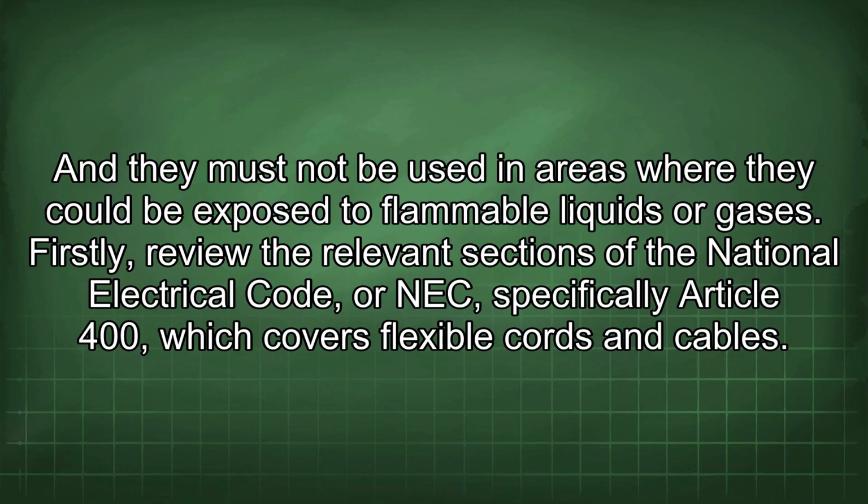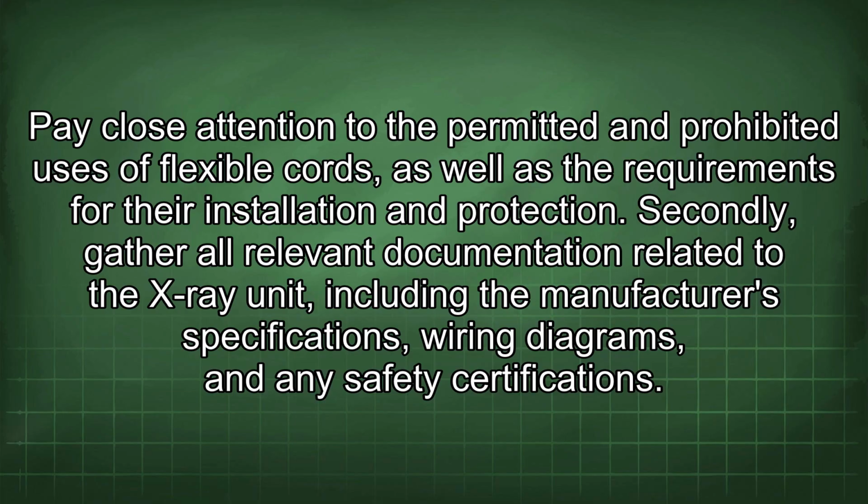Firstly, review the relevant sections of the National Electrical Code, or NEC, specifically Article 400, which covers flexible cords and cables. Pay close attention to the permitted and prohibited uses of flexible cords, as well as the requirements for their installation and protection. Secondly, gather all relevant documentation related to the X-ray unit, including the manufacturer's specifications, wiring diagrams, and any safety certifications.